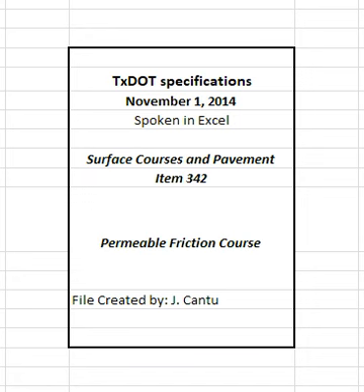5.1 Asphalt. The asphalt weight in tons will be determined from the total weight of PFC. Measured asphalt percentage will be obtained using Tex-236-F or asphalt mass flow meter readings for PG76 mixtures, as determined by the engineer. Measured asphalt percentage will be obtained using asphalt mass flow meter readings for AR mixtures. Provide the engineer with a daily summary of the asphalt mass flow meter readings for AR mixtures unless otherwise directed. Add the recycled binder content to the flow meter readings when calculating asphalt quantities.